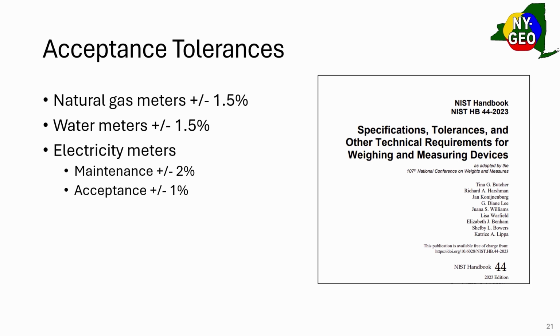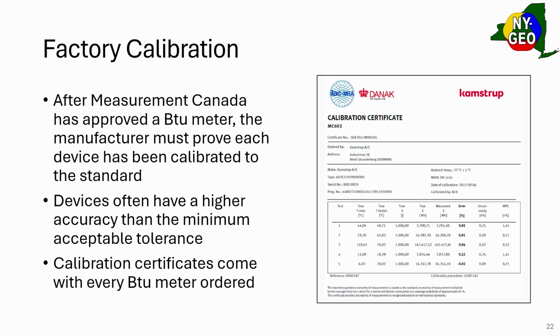We'll get into the low delta T consideration, but it is comparable, and in terms of price it's relatively comparable as well, because you can think of a water meter for a 2-inch pipe versus a 3/4 inch pipe or a 1/4 inch pipe. It's a different cost, and these BTU meters are as well. They scale with the pipe size in terms of cost.